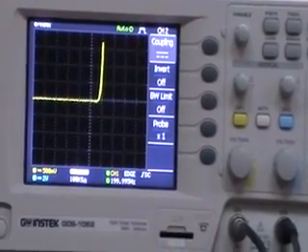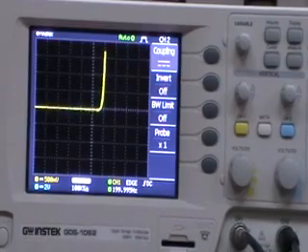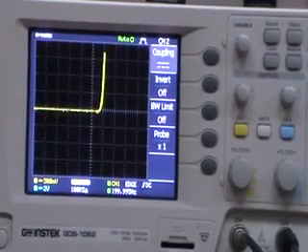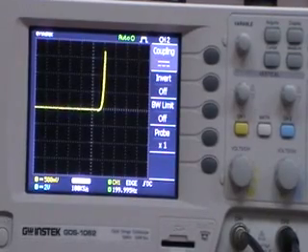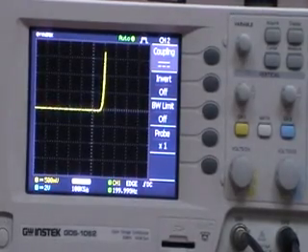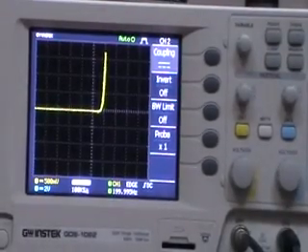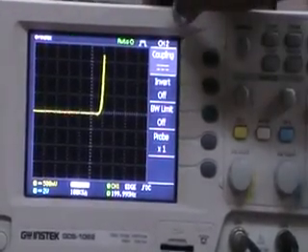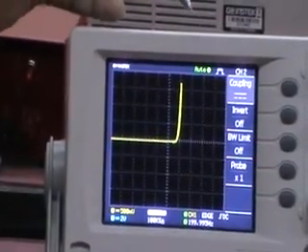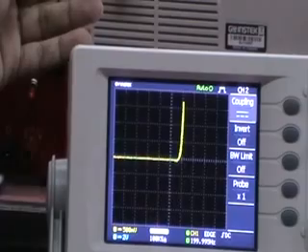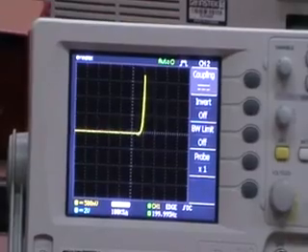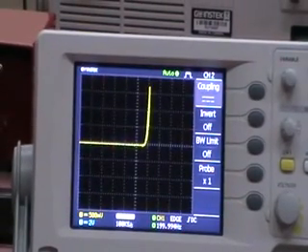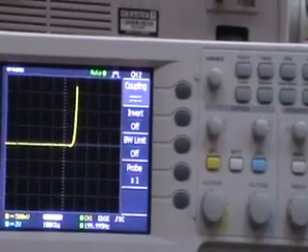Next, we have to draw all these diode characteristics and note down all the salient points. The final step of this experiment is to find the diode forward resistance by measuring the slope of the conductive region. In this linear region, we should take two V points and I points, and by finding the slope of V and I, we will find the diode forward resistance.